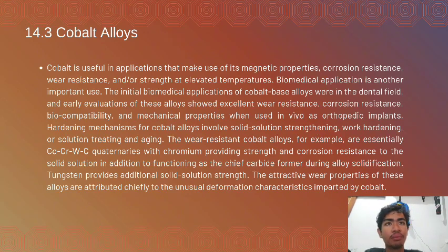13.3 The cobalt alloy. Cobalt is useful in applications that make use of its magnetic properties, corrosion resistance, wear resistance, and/or strength at elevated temperatures. Biomedical application is another important use. The initial biomedical applications of cobalt-based alloys were in the dental field, and early evaluation of these alloys showed excellent wear resistance, corrosion resistance, biocompatibility, and mechanical properties when used as orthopedic implants.